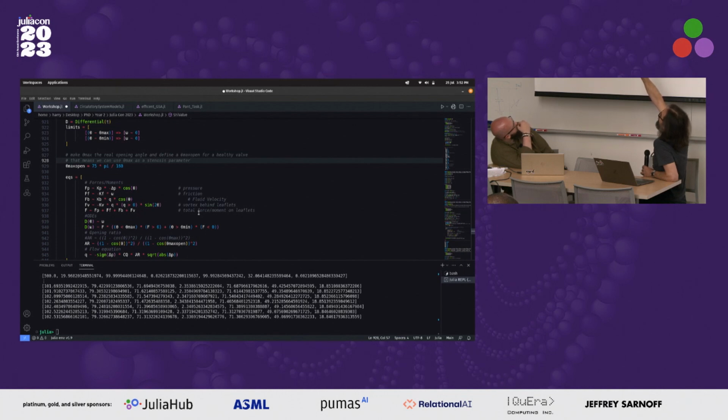So the limits definition up there is for a callback, an internal callback within that element. So when the theta angle, the opening angle, reaches maximum, then we set omega to 0. So then it stops moving. That's a hard stop. That's part of the published model, and we see that in the results. So it runs into a hard door stop, basically, and the same when theta is theta min, then omega becomes 0. So we have two hard door stops in this.